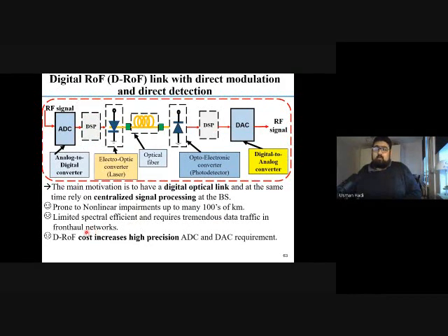It is good that there are no nonlinearity issues, you can use it to hundreds of kilometers, and the data traffic is a lot. But the problem is that the resolutions of the ADCs and DACs increase the precision of the system, and as we know, it is 2 to the power n, so as the resolution increases, the cost will increase as well. That is the limiting point for the digital one.